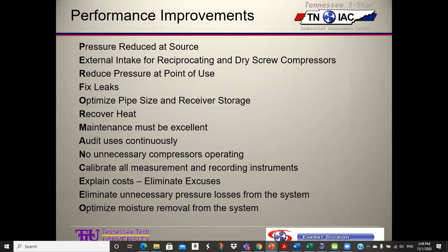Performance improvements, well, this is kind of a laundry list. Reduce pressure, external intake for reciprocating and dry screw compressors, i.e. maybe get cooler air into them, can help. Reduce pressure at point of use, fix leaks, optimize pipe size and receiver storage, recover heat. Maintenance must be excellent.